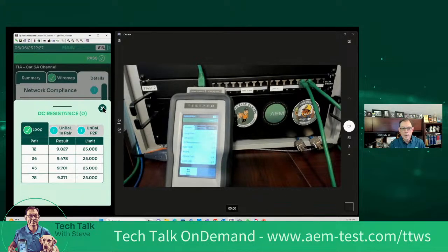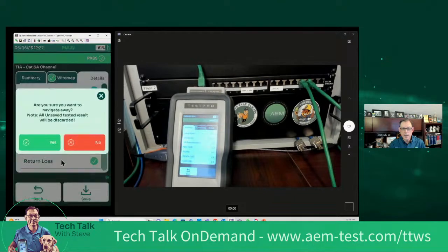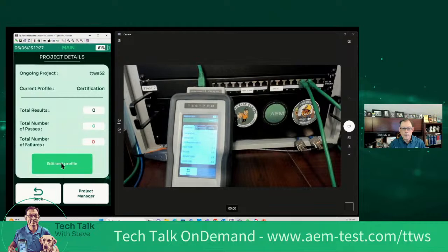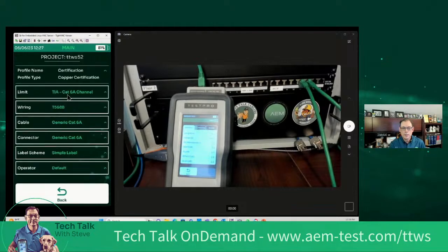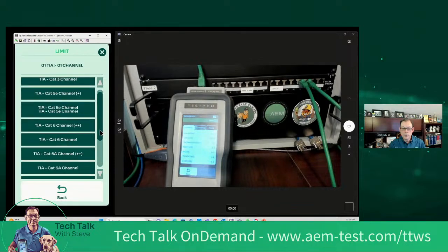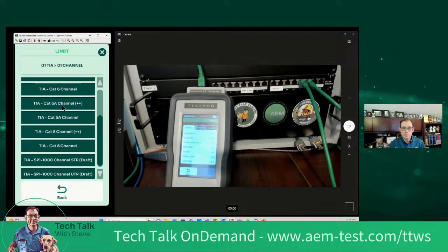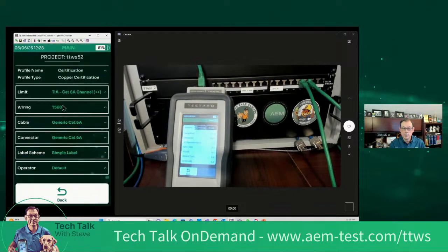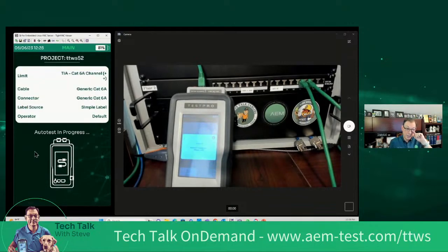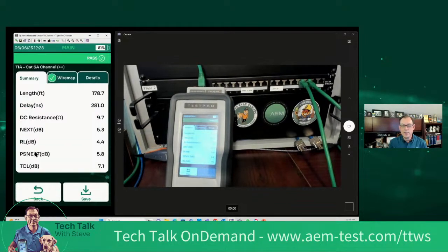So what I'm going to do now is I'm going to back out of this. I'm not going to worry about saving this test. I'm going to quickly edit my test profile. And I'm going to change this. And instead of doing the regular Cat 6A channel, I'm going to choose this Cat 6A channel plus. And then this is going to give me my DC resistance unbalance weighted with a pass fail. So we'll run that test again. And again, it's still only going to take 6 seconds. We're not adding any time to do this.